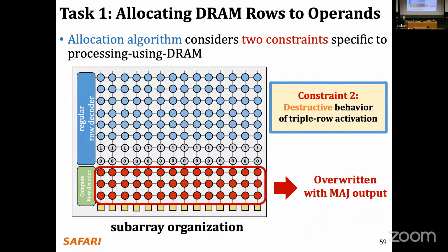So I'm going to activate this first one, these others, like say row 0 and row 2, and then I'm going to have the carry of that particular bit stored in this column. And then for the next bit, it's the same operation, but now I'm going to activate this row indexed 1 here, together with the row indexed 3, plus the carry that was generated in the previous step. So activate the 3 of them for generating bit 1, plus the carry out, right? Because it's 2 bits in this case.